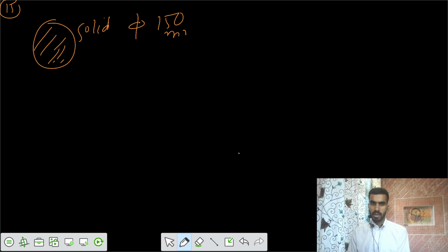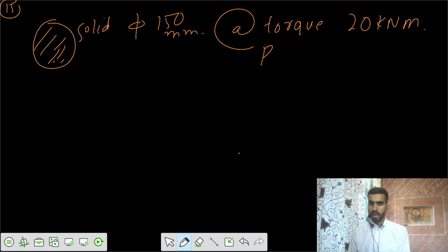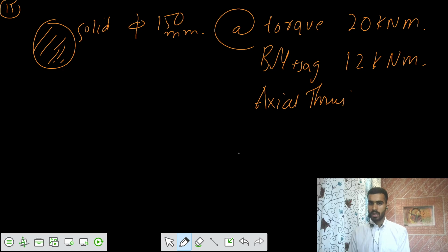So we have problem 15. There is a solid section with diameter 150 millimeter, and you are applying a torque of 20 kilonewton meter, and also a positive sagging bending moment of 12 kilonewton meter, and you are also applying an axial thrust. Let's assume that it's tensile, 200 kilonewton. So this is a positive moment, and this is a tensile force of 200.